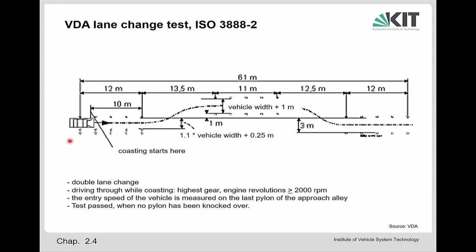And if I do this steering so fast that my roll angle, because of this resonance, gets so large that the full deflection range of the spring on this wheel, of the body spring of this wheel, will be needed.